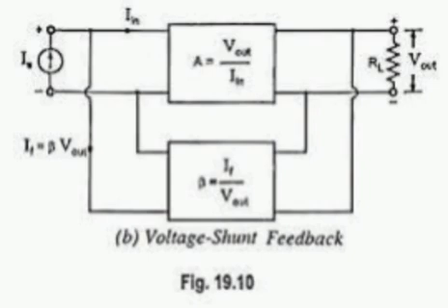Analysis of large signal amplifier. Load line analysis for common emitter amplifier, where ICQ equal to quiescent collector current, VCEQ means quiescent collector emitter voltage, Thevenin resistance driving base, RB equal to RS parallel with R1 parallel with R2, AC load resistance seen by collector, rc equal to capital RC parallel with RL.